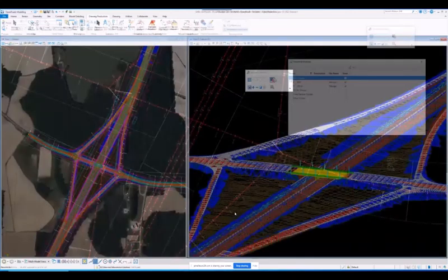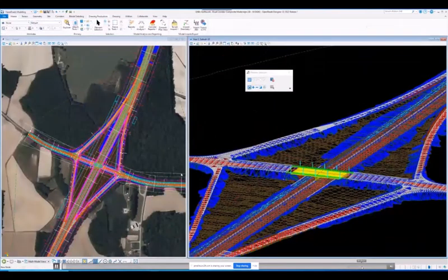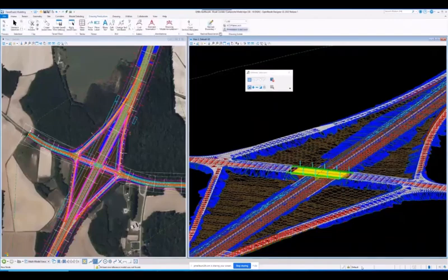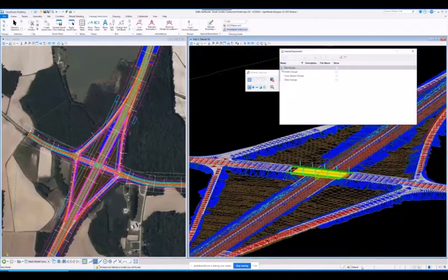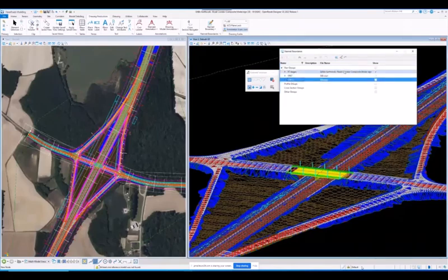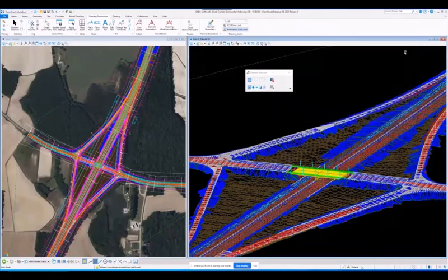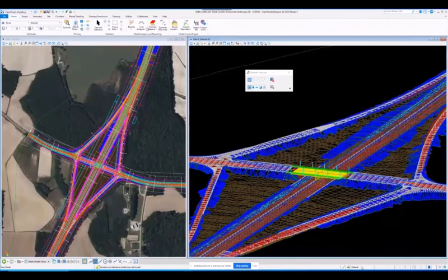So at that point, taking that, we can start breaking that model up and digesting it. And really that's the key here. We featurized everything. We told everything how it's supposed to look, level, color, weight, but with the additional properties they're putting on these meshes, even the linears, we know what it is. So I'm going to start chopping up this model and run some reports. In this case, I'm going to go to the civil analysis tools, create name boundary. I'm going to pick I-95 here, select that, and run this through.